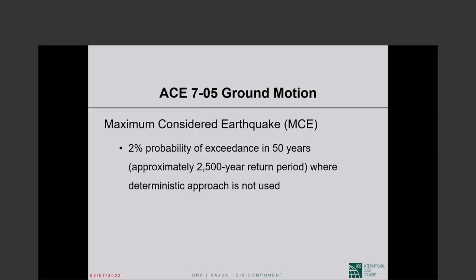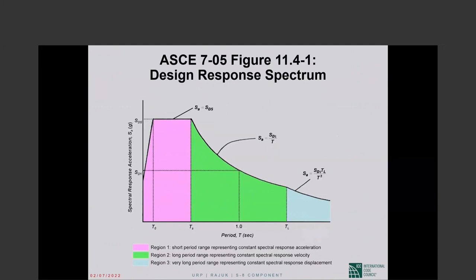So this is the maximum considered earthquake for our purposes in Bangladesh. This is the 2,500-year return period earthquake, 2,475 years to be more exact. So we come back to the design spectrum, or the design response spectrum, of ASCE 7.